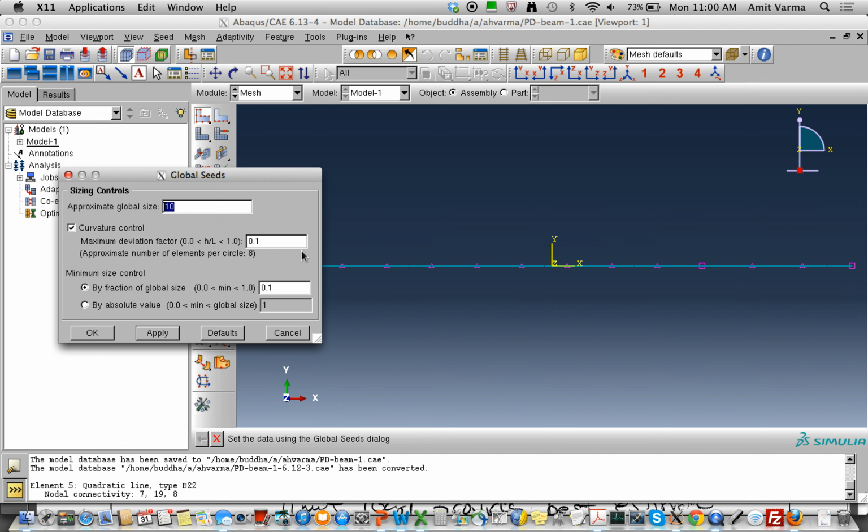It's the thing that we've just been talking about, whether it's in load control, whether you're using modified Newton-Raphson, or you're using the Riks method of analysis, or implicit methods, or explicit methods. If your solver is incapable of working with so many degrees of freedom, you're going to run into situations where your finite element model will be running for quite a period of time. Which means that it would behoove you to use a program that has robust solution strategies.